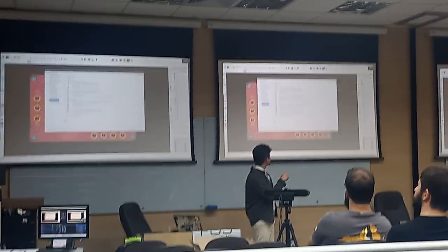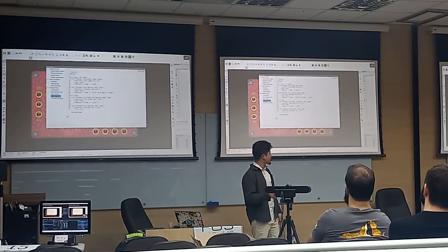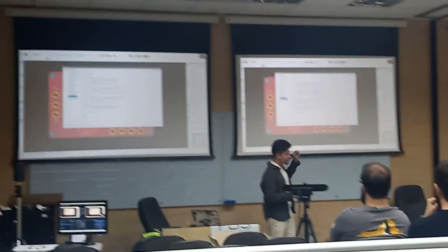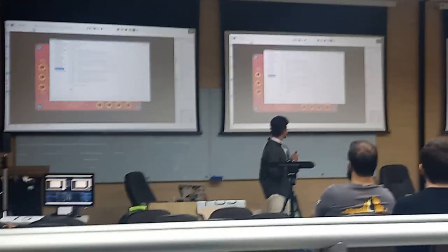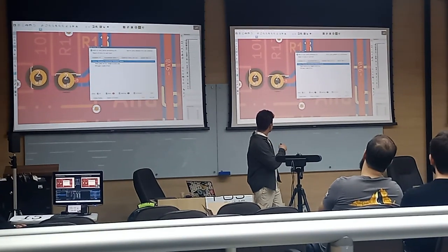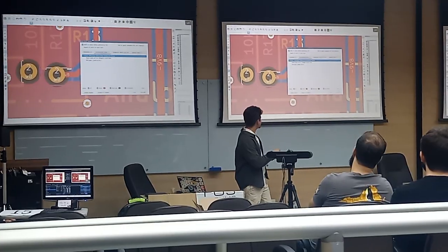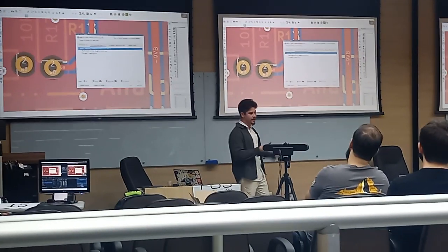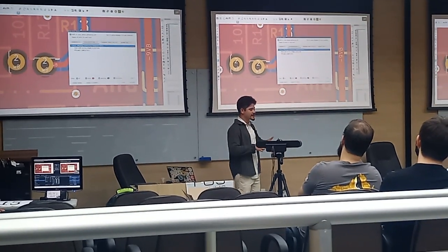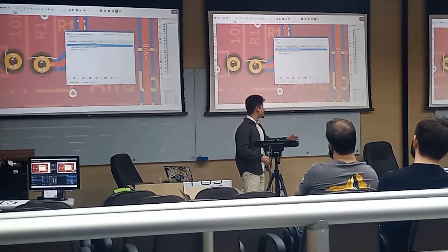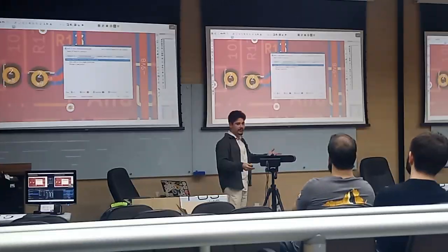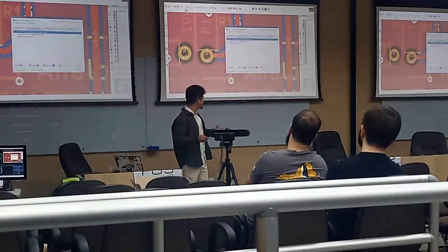I didn't write this on my own. The reference is on GitHub. This is the repository where I found this code, from some guy on GitHub, and you can do this and the DRC will work. This is an unconnected circuit. It is warning me: missing connection between items. Very intuitive. I will emphasize this because in some tools the error is not intuitive. They don't say anything besides an error, find it yourself. But this says this thing is unconnected, very clear, very easy to work with.